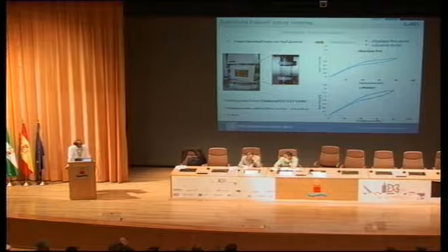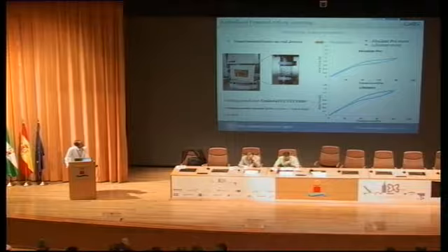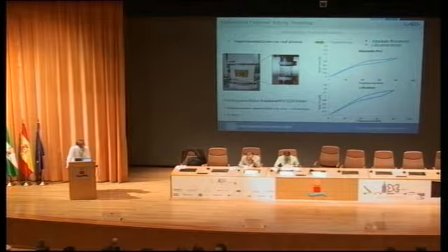What we did, here is an example of some tests that we did. We did them in terms of axial force versus displacement, and for 2 different stents, and these are the curves that you can obtain from an experimental campaign. Another important thing is that when you do experiments with nitinol, these are very sensitive to the temperature, so you have to control also the temperature. This test has been done at 37 degrees, which is body temperature.